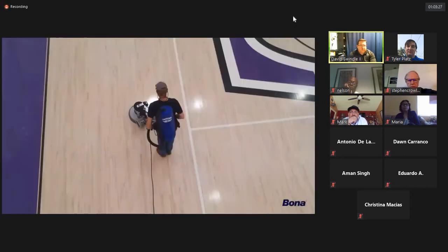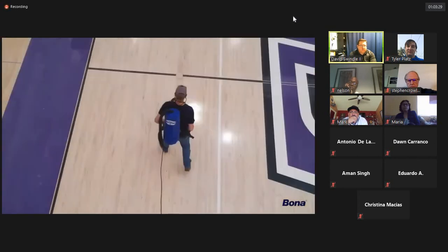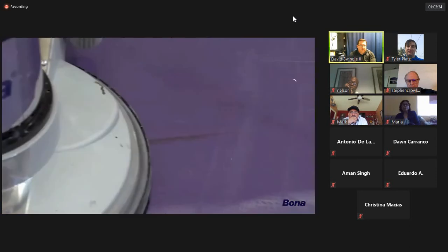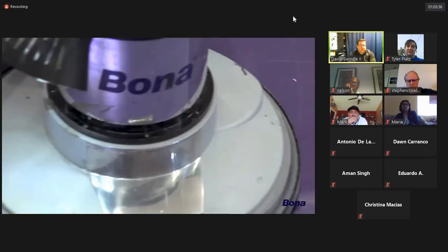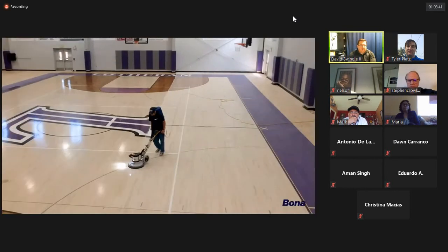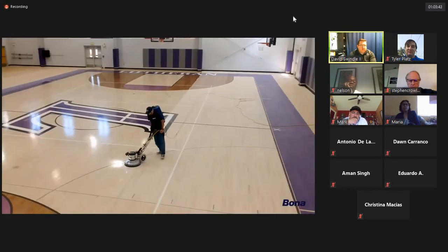While abrading, move at an even pace and work with the direction of the flooring, overlapping each pass by at least 6 inches. Make sure to remove all scuff marks and any other flaws that are on the surface. All gloss or sheen on the floor should be completely removed during the abrasion process.